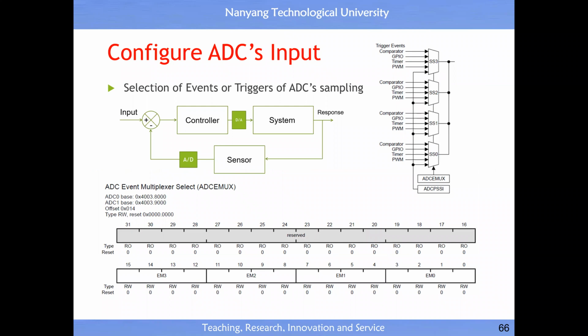And then for each sampling device, either you can turn it on and off by software, or let the hardware turn it on and off. Why let the hardware do it? It's because once you turn on your controller, automatically the sensor must turn on and off. So there is an intrinsic hardware synchronization.